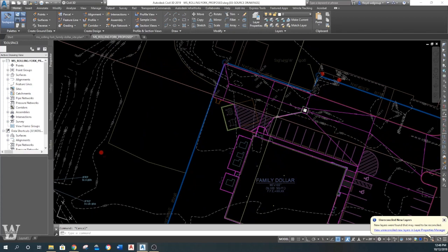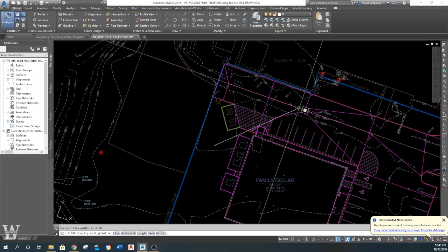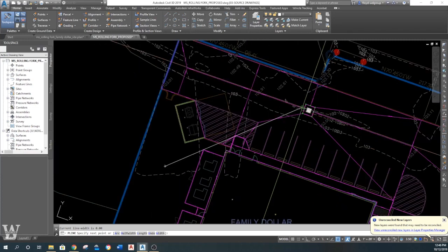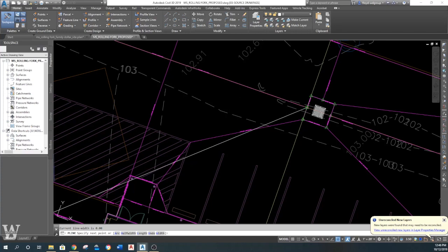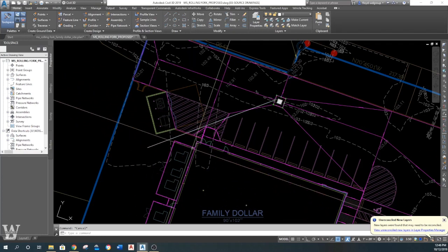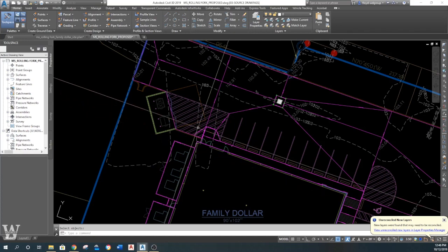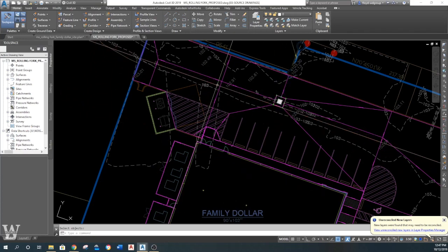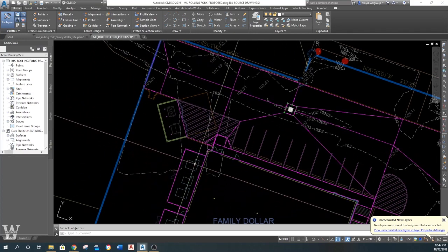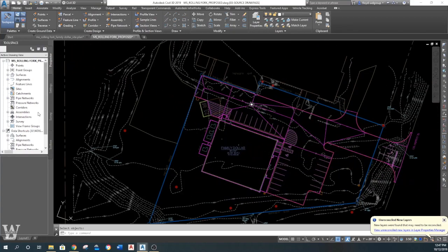And if I come right here, okay, so what that does is it'll let me not have to put another inlet in. I can come in here and make my pond right in this area somewhere, so I can discharge my pipe out of there. Those are the kind of things I want to make sure of. Otherwise, I want to shift this down some so I can pull it out and not have to have but one inlet in. All right, so let's see if that works.